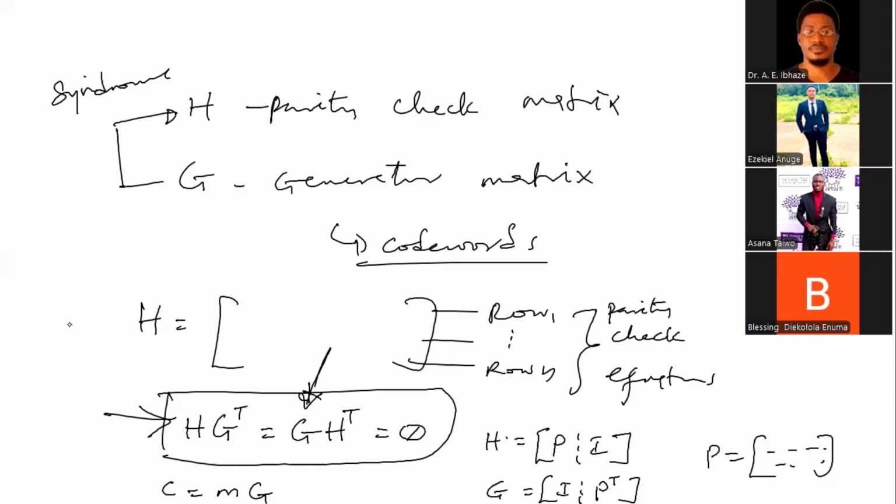So now, if that's that, then how do we perform the low density parity check code decoding? Like I mentioned, for us to be able to decode the LDPC codes, we use the belief propagation algorithm, which is also known as message passing.